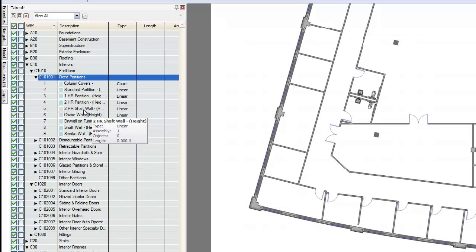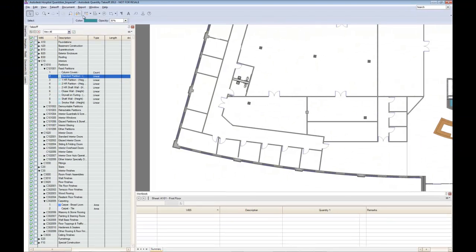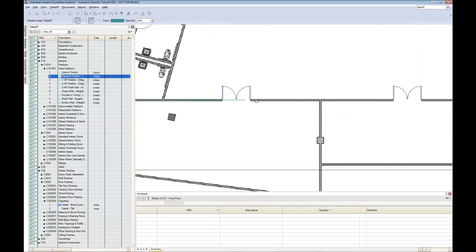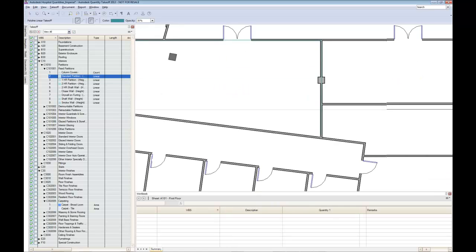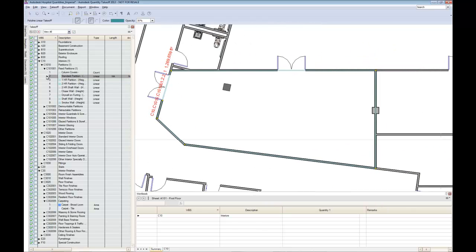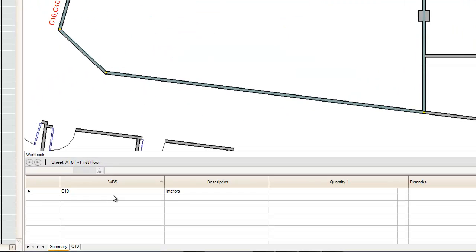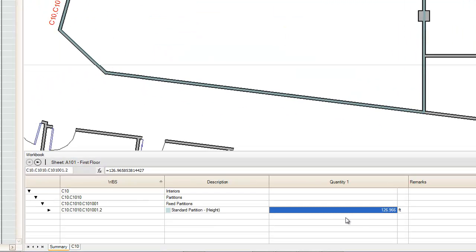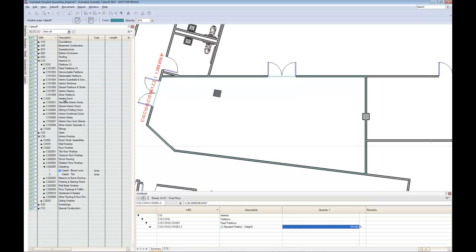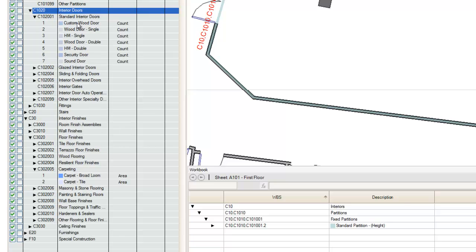We will leverage a catalog of standard building components to begin to quantify and classify the data provided using two-dimensional takeoff tools. Note we can do linear takeoffs for things like walls and partitions, and that once digitized, we get a worksheet of the quantities generated that keeps a running tally of the information. We are also given a visual component to show what parts of the plan have been taken off or traced already. The process simply repeats for other components, like a count for the doors or an area takeoff for the carpet in these offices.